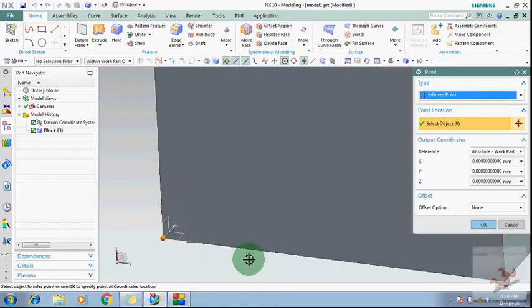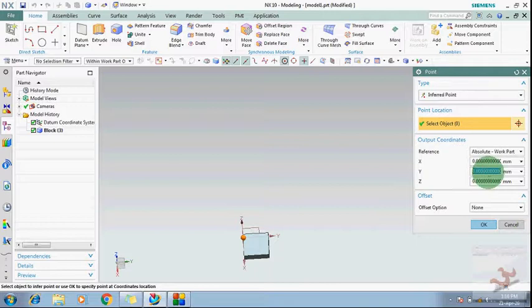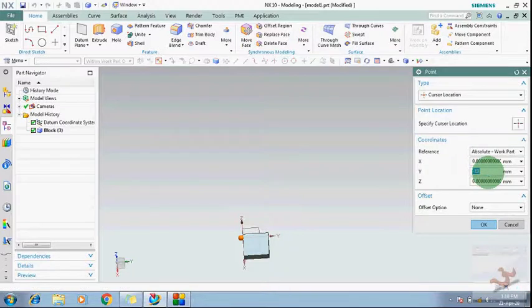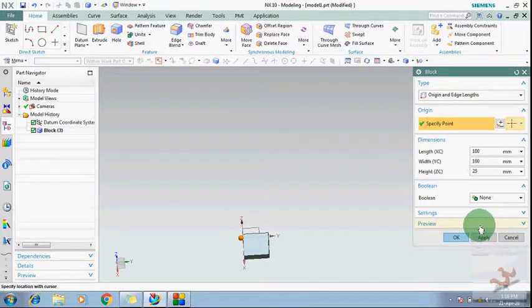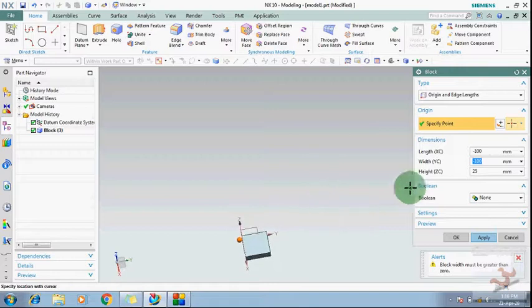And this is the y. I want to move it in y direction. Suppose that minus 10, and then okay, and then negative all these dimensions so that your block will be in the opposite direction. Or you can move the face with the minus 10.